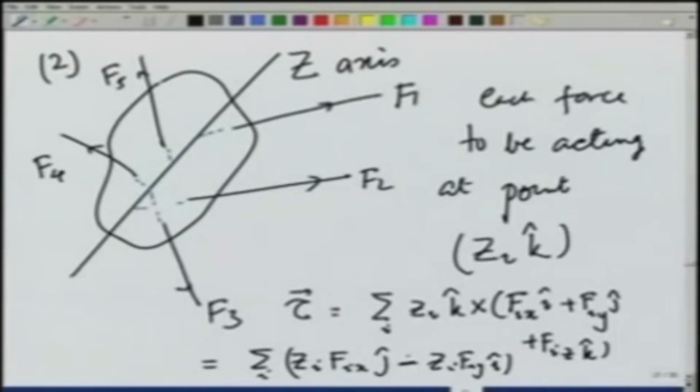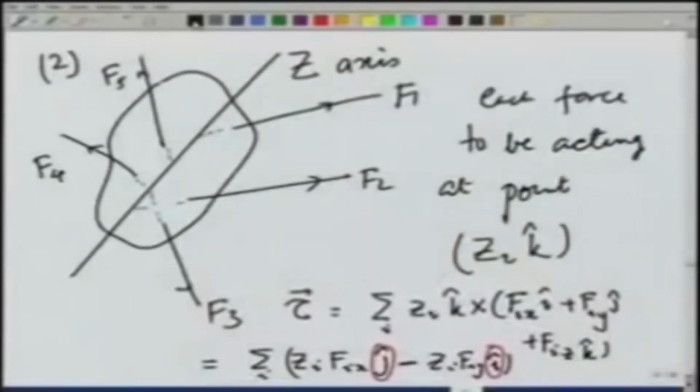So, you see the only components of torque, for such forces that are all intersecting one particular line which we take to be the z axis, are in the directions x and y only, and therefore, we need not worry about the condition that summation tau z is 0. Such forces are called concurrent on a line. So, forces concurrent on a line give me torque tau z equal to 0. So, let us rewrite it.